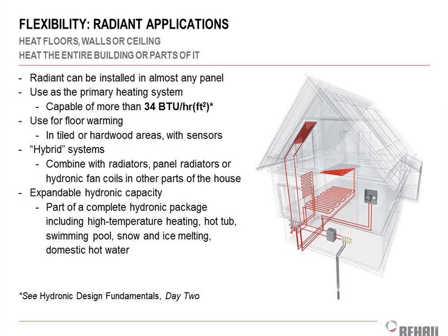More advanced ways exist now, right? There's clamps you can install on the ceiling, or now we have these aluminum tray panels. One of our manufacturers, Rehau, makes one called Raupanel. Those are very nice because you nail that panel up to the bottom of your floor from underneath, and you lay the tubing inside that metal panel. And that metal panel spreads out the heat more evenly. All right, so you can do that to temper your floors if you want to.